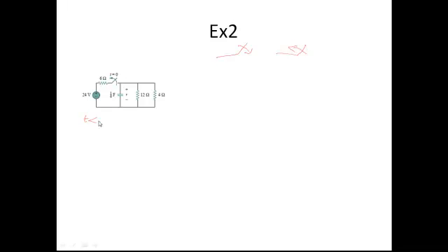So now I will draw two circuits. One is time t lesser than 0, another one is time t greater than 0. In time t lesser than 0, what is the position of the switch? It is closed. Okay, so the circuit is like this. This is 12 ohm, 4 ohm, 6 ohm, 1 by 6, 24. And for time t greater than 0, the switch is open. Therefore, the source is disconnected from the rest of the circuit. So your circuit is now like this only.